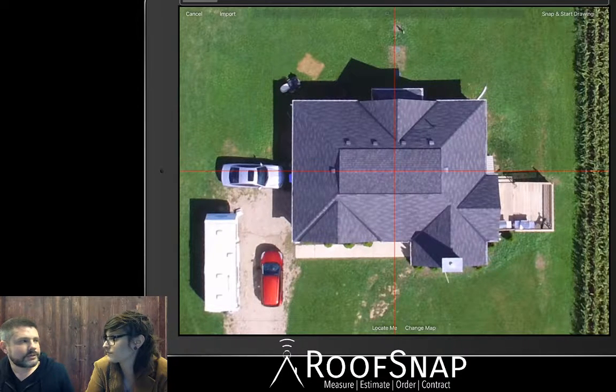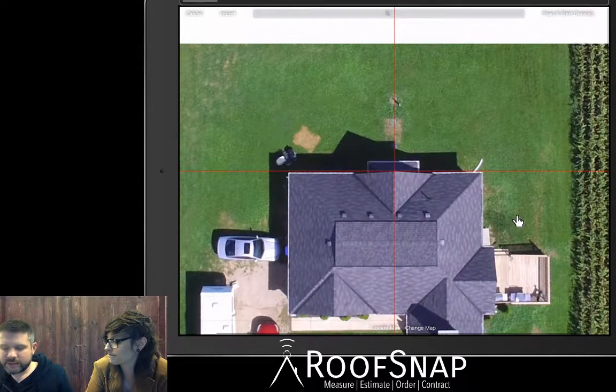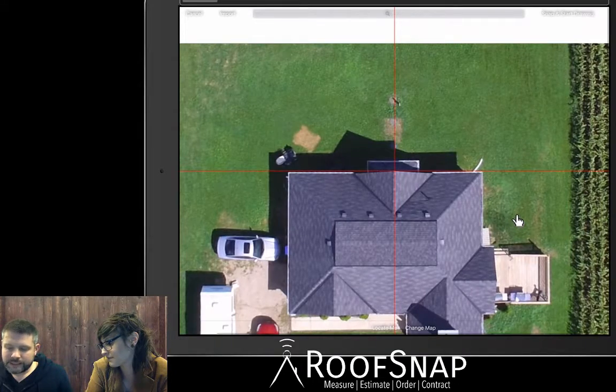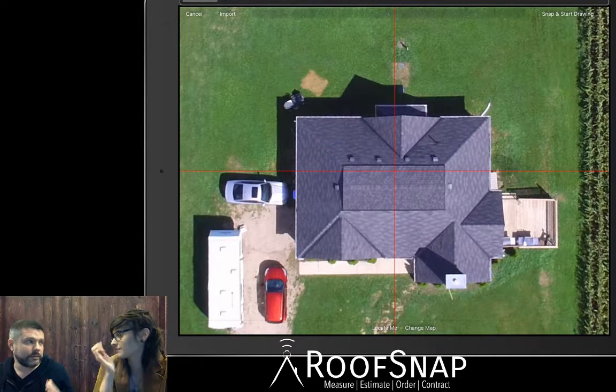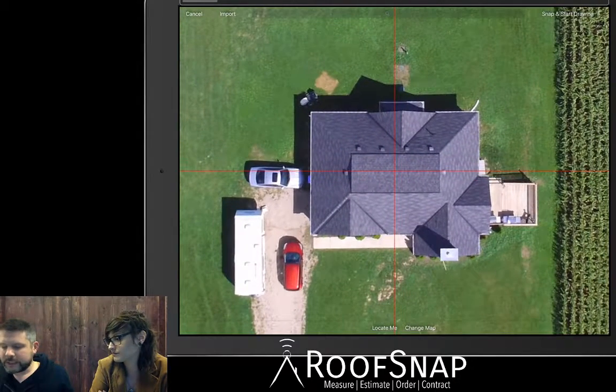That is sort of the ceiling that's been allowed by the FAA for this type of drone piloting. But what you'll see here is this rake in particular has a pretty substantial angle to it. Right. And it's skewed because we're too close. If we were 20 feet off of the roof top, it would be extremely distorted, and you would notice it immediately. So we recommend, this was probably taken somewhere around 200 feet.